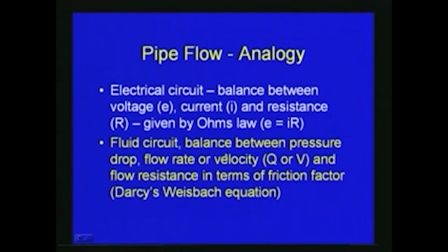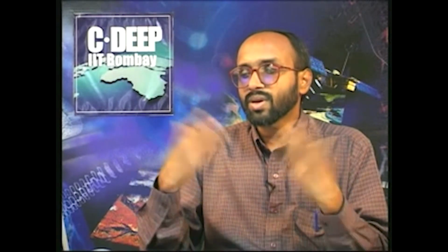So, we can have one-to-one correspondence with the electrical circuit. If you just consider Ohm's law, we can make an analogy with the fluid circuit: we can compare the pressure drop with the voltage, the flow or velocity with the current, and the resistance in an electrical circuit with the flow resistance in terms of the friction factor, and compare with the Darcy-Weisbach equation which we have seen earlier with the corresponding electrical circuit system. Like that we can have an analogy, and then we can try to use this analogy for the solution of